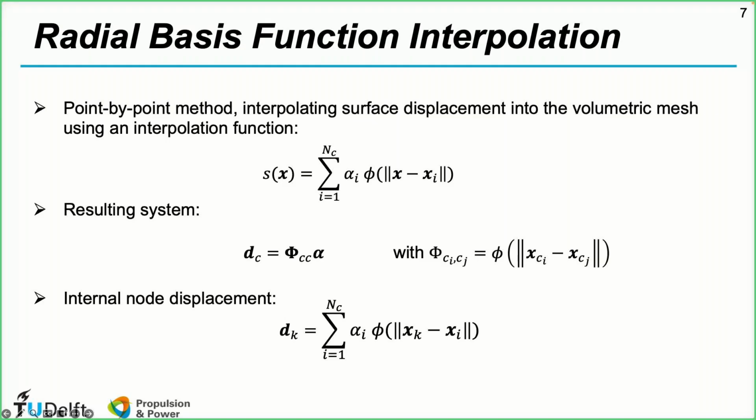Once you've set up the system, you can then solve for the interpolation coefficients, and that allows you to find the internal node displacements by simply evaluating this interpolation function for your internal nodes.